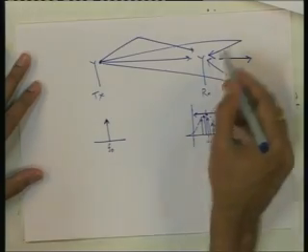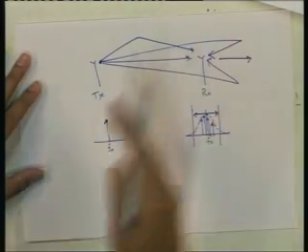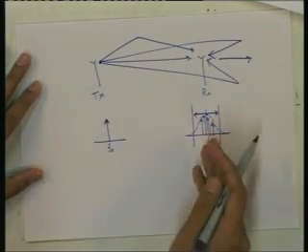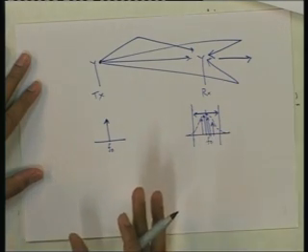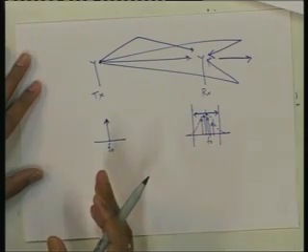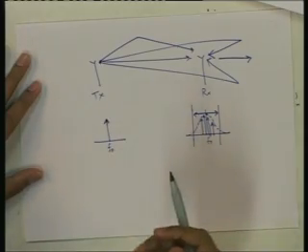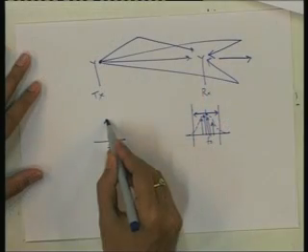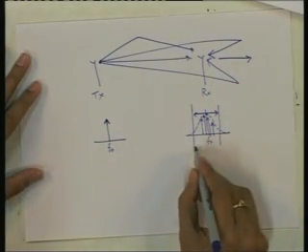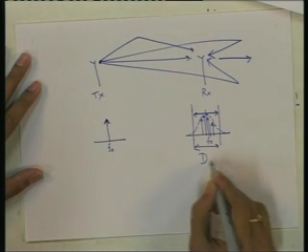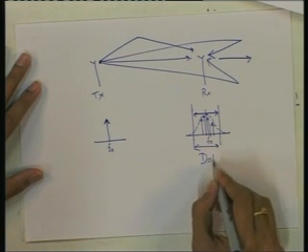We know that this shift of frequency is called the Doppler shift, but in this case there will not be a Doppler shift, but there will be a Doppler spread of the signal, because the frequency along some paths is decreasing and the frequency along some other paths is increasing, and as a result the transmitted signal on a single frequency will be spread out in a band of frequency, and this band is called the Doppler spread.